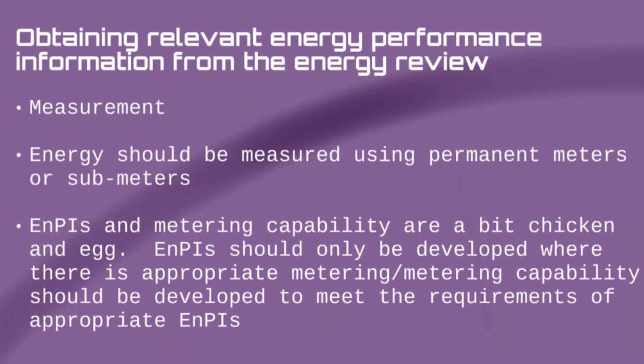Energy performance indicators and metering capability, sub-metering capability specifically, are a bit chicken and egg. Energy performance indicators should only be developed where you've got appropriate metering, and metering capability should be developed to meet the requirements of appropriate energy performance indicators.